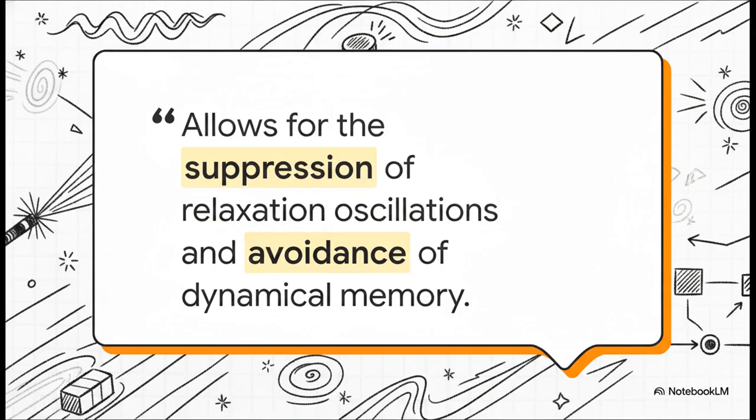By mathematically shaping that current, they ensure that at the end of every single bit of data, both the photon density and the hidden carrier density are forced back to a known, stable fixed point. The laser completely forgets the previous bit. Zero memory, zero overlapping, and zero muddy noise. It's just an incredibly elegant software solution to a deeply physical problem.